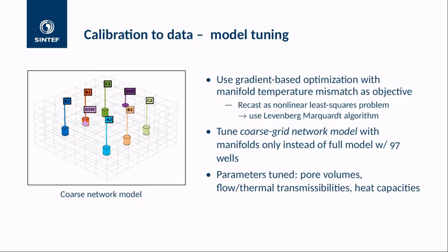Another application of the platform is in calibrating to measured data. I'll use a different example that was presented by Ruden before. It's a representation of one of the geological reservoirs that they are working on at the Vestkvartalet in Asker. So here we have actually measured data for a year of production temperatures, and we are trying to reproduce that using our simulator. We have here a relatively conceptually simple representation of the shallow reservoir that they have there. In reality it's like 100 wells or so. We are using each well group as a separate well in order to simplify the problem.